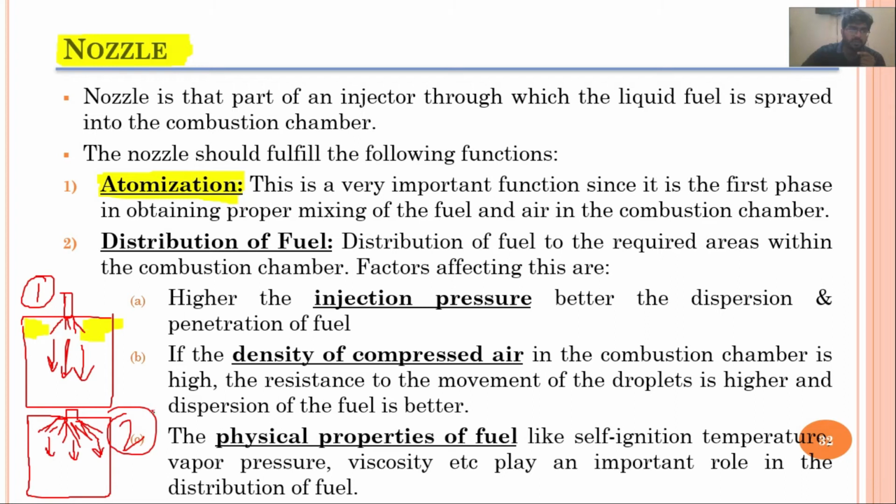So what will happen here is, if we decrease the size of the orifice, we can increase the spray of the nozzle, and by increasing the pressure of the injection pump, we can penetrate this dense air up to the piston, so that the entire amount of air which has been compressed can be utilized for this purpose.